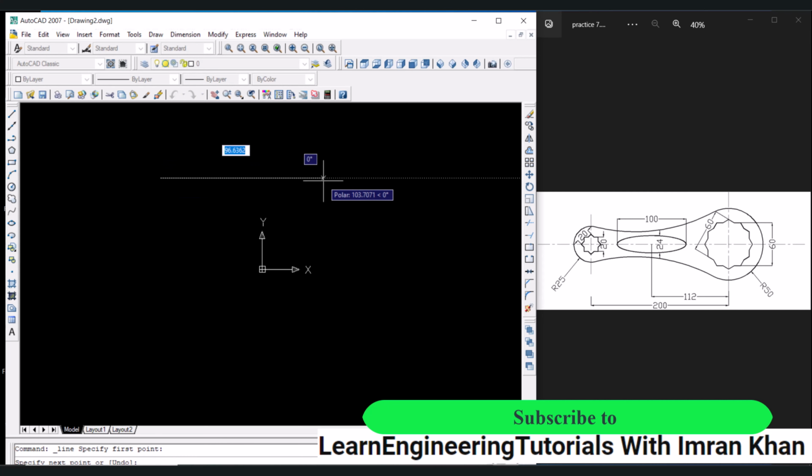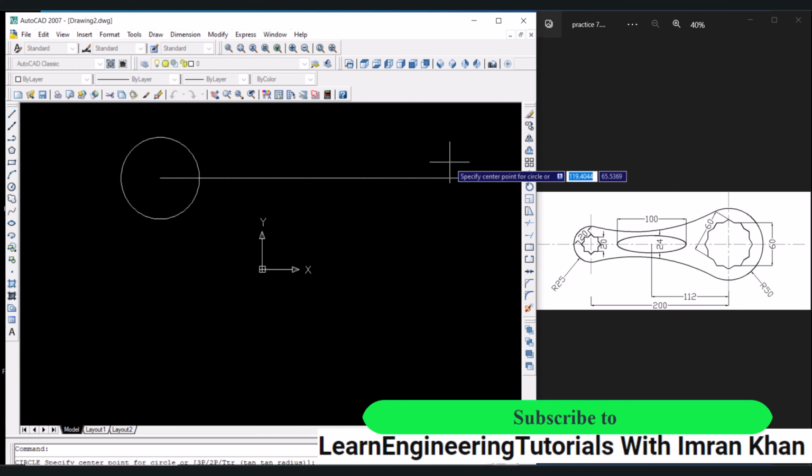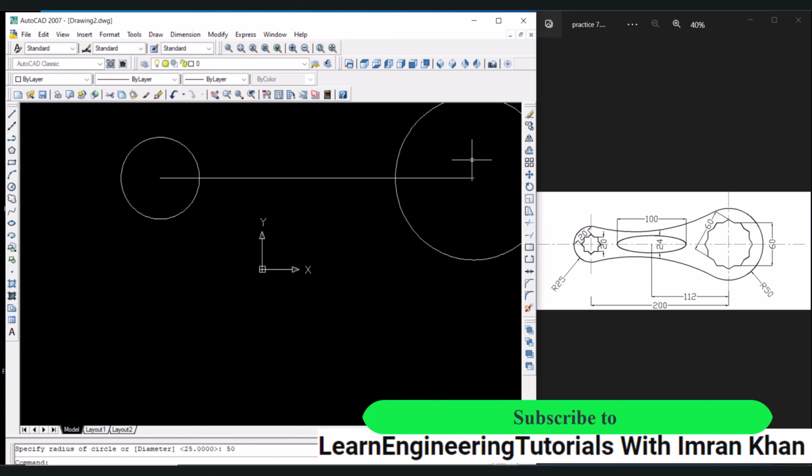click anywhere, give the value in the X direction as 200, enter to get out of the command. Now this line is actually a reference line, so draw a circle over each end. So click on the circle icon, bring the cursor over this end, click, and now give the radius of 25, enter. Press enter again, bring the cursor over this end, click, and this time give the radius of 50, enter.